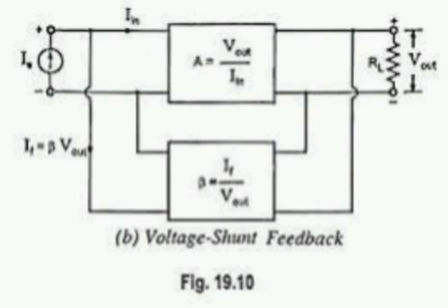High frequency analysis of FET amplifier. It is performed by considering the effect of small capacitors. Small capacitors mean the external shunt capacitor C shunt and internal FET capacitances CGS, CGD, and CDS. CGD is the transition capacitance of the gate channel junction. CDS means internal capacitance of the channel. Small signal high frequency equivalent of FET amplifier.